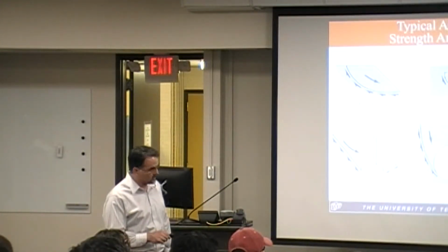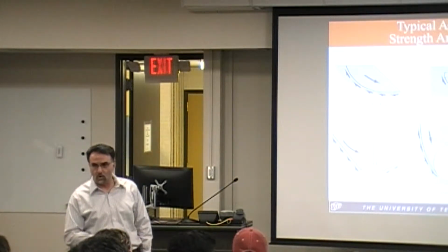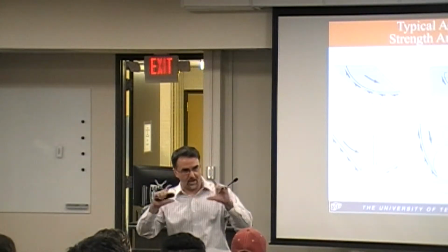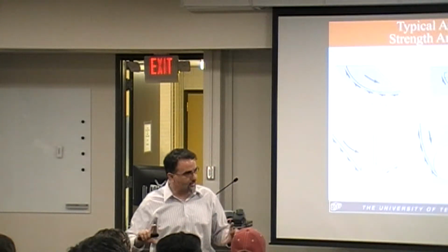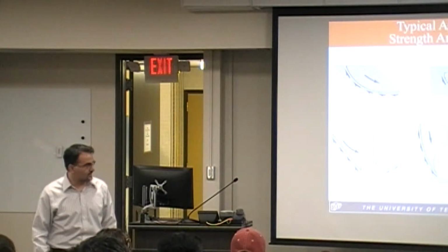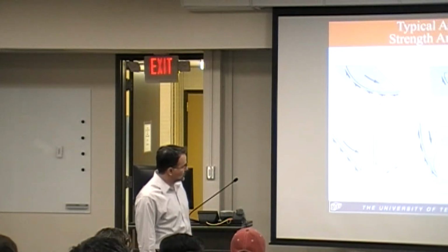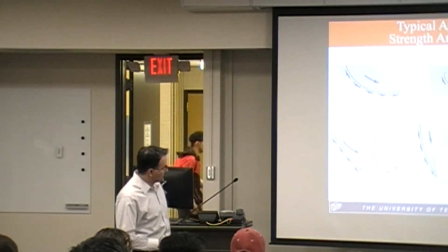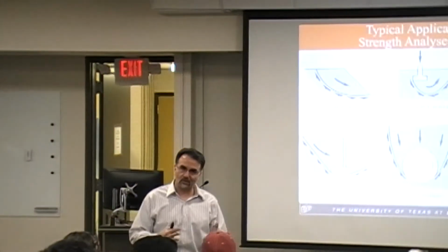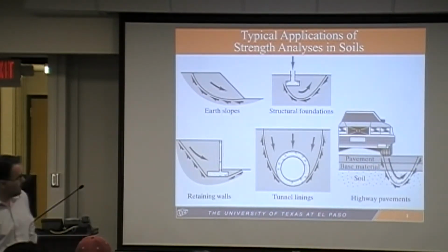We do have information about the pavement here. You want to make sure that the stresses induced by this wheel load are not going to induce failure in this multi-layer structure. This is a little bit different from the other types of structures, because you have different modulus values, or different stiffness properties, in different layers. That's the reason that the nature of contact between these layers is also going to be a factor when you are doing the analysis. And ultimately, we do have tunneling. If you have buried structures or tunnels in general, you also have to make sure that the soil around and above it is not moving. Otherwise, you're going to see failure in the material.